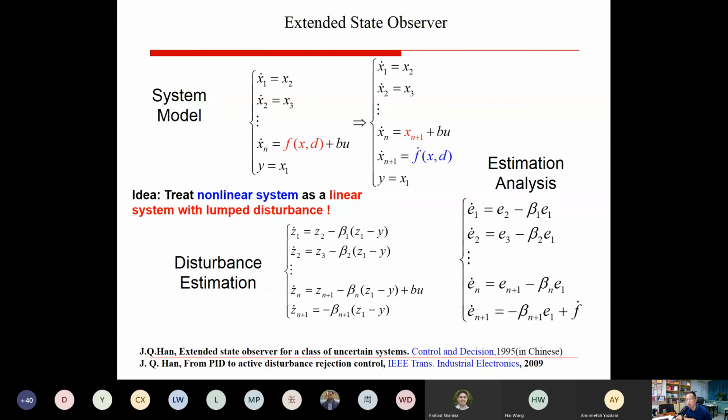Because a general servo driver needs to adapt to different working conditions. If the gain is not large enough, the control saturation just comes in the first stage where the error is big. Most working cases, like manufacturing, work at a constant reference speed. Then the system works in the steady state. The control saturation in this case is not a big problem, because only in the starting stage is the error big, and then the control input is big. But I do recognize there are some cases where you have a big error or a big load torque, and maybe you will meet control input saturation.